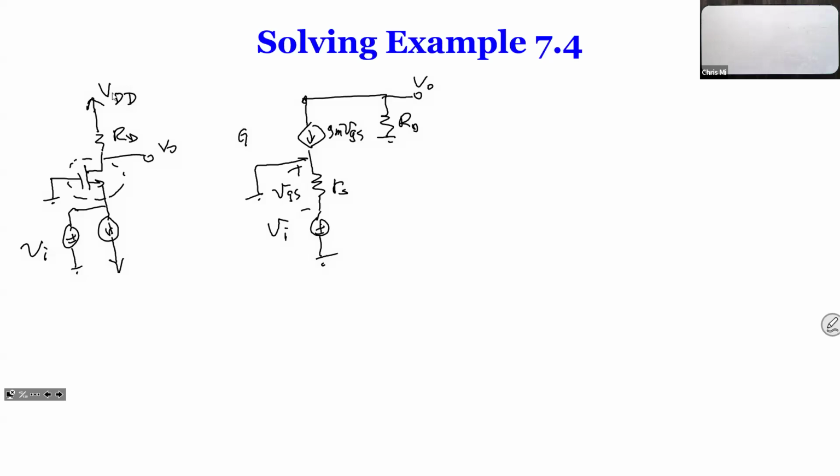So this is important because you don't treat it as saying VGS equals VI. Actually it's not. VGS is from gate to source. The reason is your source is right in the middle here, and your drain is at the top. So your source is not at the ground. VGS equals negative VI. In this case, we need to find out what VGS is.